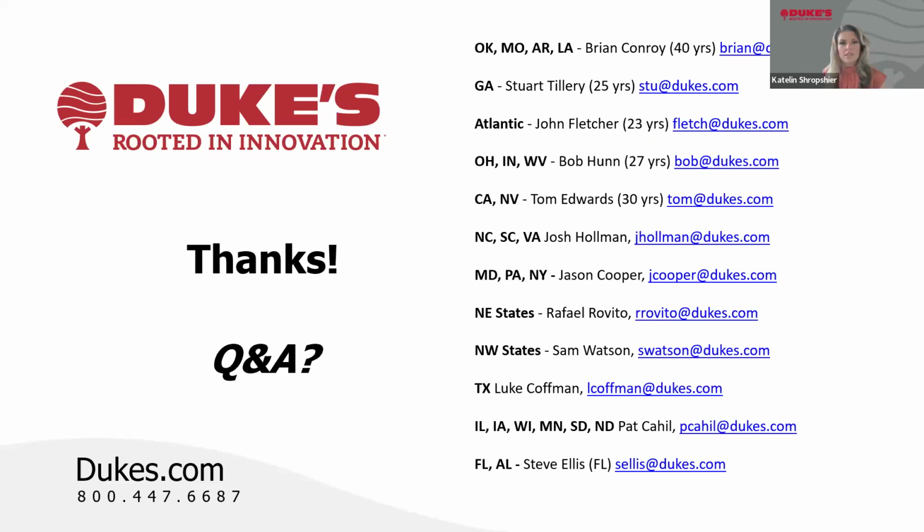Someone else asked, when applying chemical root control, should you cut the roots mechanically first, or does it matter if you cut first? Yeah, you need to not cut the root first, for sure. There's more surface area, and the product needs to be on the root to be able to take care of it. So most definitely it's better to not cut it. And then last, I'll add quickly, typically the root will be killed within 24, 48 hours. And then the root typically is gone in the 60 to 120-day range. It dies, decays, and just sloughs off and goes away in that time frame.